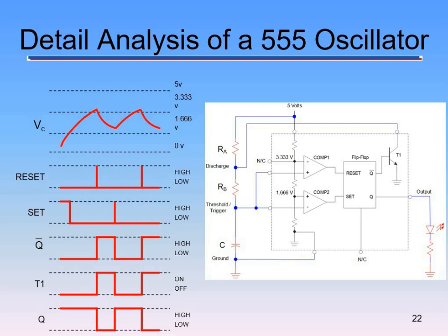So the set reset is not you physically hitting a set and reset button. The set reset's a flip-flop that's internal to the 555 timer, and the transistor is the one that's sitting there changing the values. So that's how we use electronic switching to go back and forth. That's why transistors were a huge difference maker in the electronics world a while back. And that's why you can have the internet and a calculator and a computer in the palm of your hand in your cell phone now, all thanks to that kind of technology.